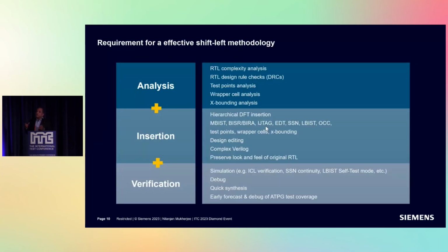So if you look at the requirements for shift left DFT methodology, what are some of the key requirements? Those can be divided into three categories. First is analysis, insertion, and verification. On the analysis side, if you are doing DFT implementation, you would like to run some of the design rule checks at RTL.